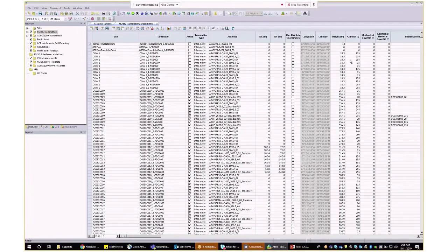As I told you, Atoll is connected to a server. When we make any changes in Atoll, we have to archive the data. If we do not archive, the changes will not be reflected in the server. As you are working on Atoll, other users who have access to the database may have modified some of the data. To ensure that you have the most recent data in your document, you have to refresh the information from the database. So how do we refresh the data?